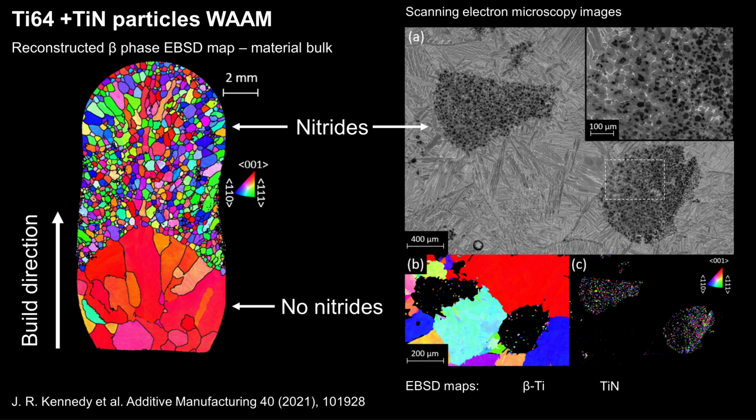The nitride particles in the liquid haven't changed the undercooling, they've just made the energy cost for grain nucleation ahead of the solid-liquid interface so low that even a smidge of an undercooling is enough here. The downside is that our microstructure is now full of brittle nitrides, so our alloy ductility and damage tolerance drop below the specification required for most applications. Not ideal.